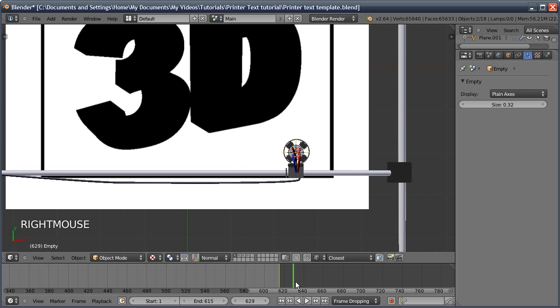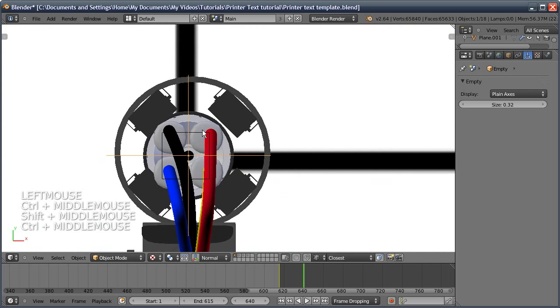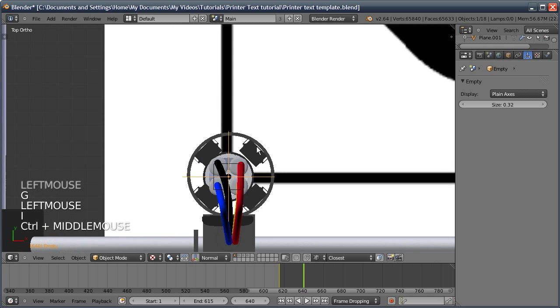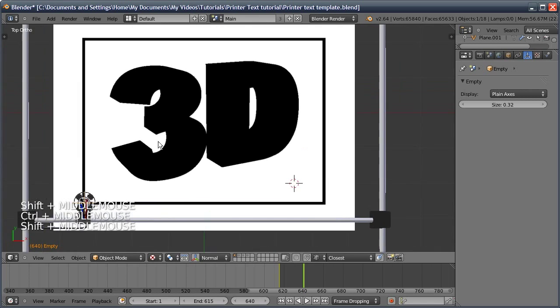and then just moving along a bit, we'll move over to our first corner, making sure this box is fully over the corner, because that's what's going to be drawing the line. We'll then press I, location, and I'm then just going to continue round doing keyframes at the corners.